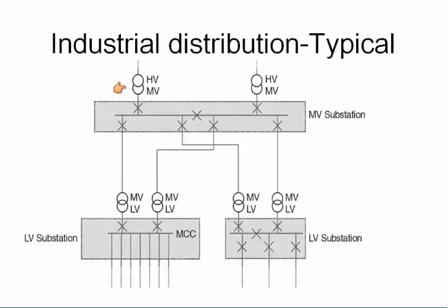Another example for redundancy, what you have here, you have two transformers. And why have you connected this in zigzag? Why does this supply go here and this supply go here? Can anyone give me the answer? Why can't we just connect them on straight lines, that coming to this and this coming to this? Why do you have this configuration where this side feeds this panel and this side feeds this panel? Maintenance, reliability, changeover, absolutely right, yes.